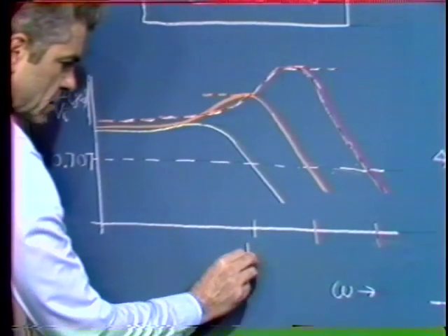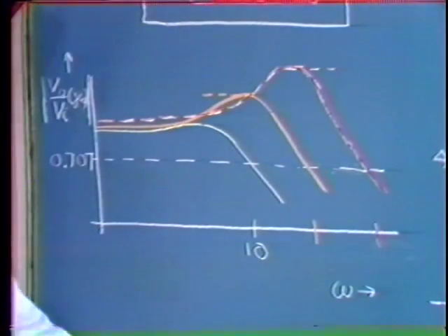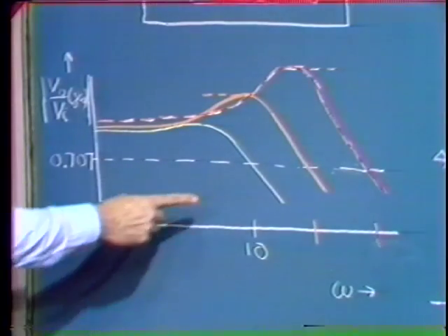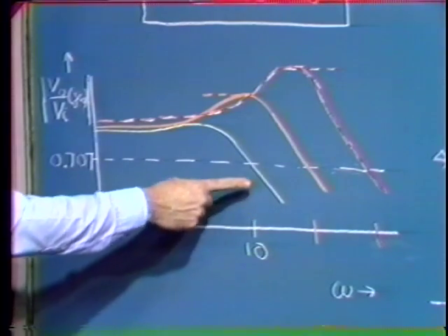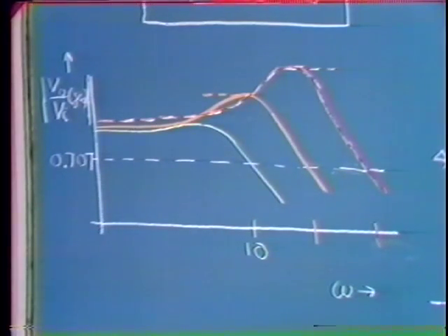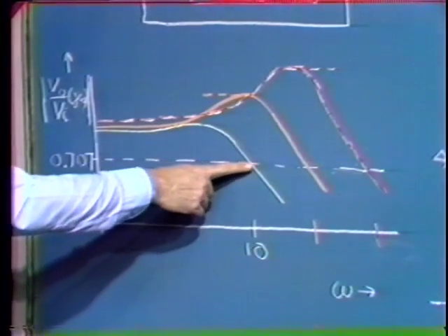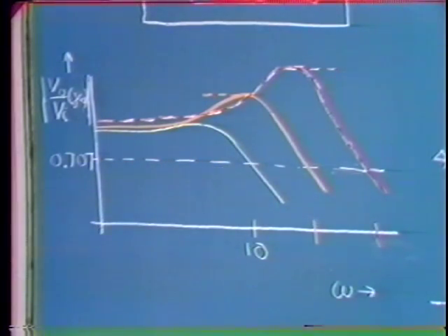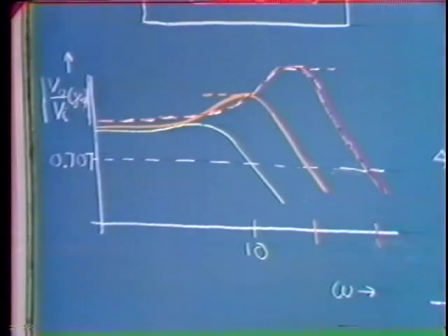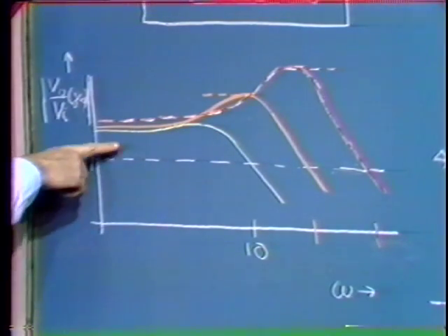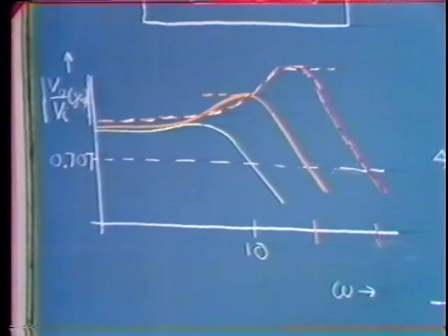So on our omega axis, we'd find out for this particular system, we had a magnitude of 0.7 at a frequency of 10. So we're able to determine a good bit from this kind of construction. We are able to determine, for example, the so-called half-power frequency of the closed-loop system. We're also able to get a very good indication of relative stability. Here we have very little peaking for A naught, F naught equals 8.5, and we conclude that's a fairly stable system. That's a very, very well-behaved system, in fact.